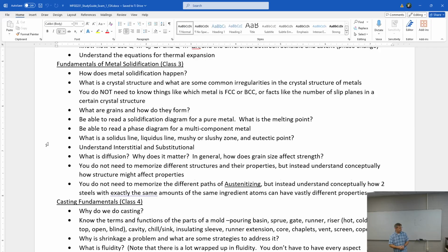All right, where are the biggest places that you deal with thermal expansion in the plastic world? Injection molding is huge because as the plastic shrinks and cools, it will shrink away from the walls if you design them correctly so that you can get the part out.